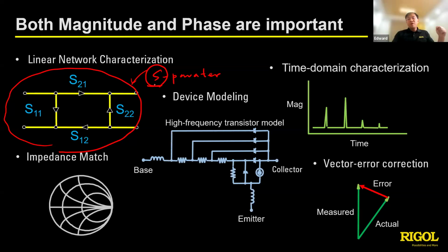The traveling wave or the signal goes from the left-hand side into the first port, like this one. If we get the reflected wave from port 1, we get the S11 parameter here. That means the first index is the receiving port and the second is the transmitting port.